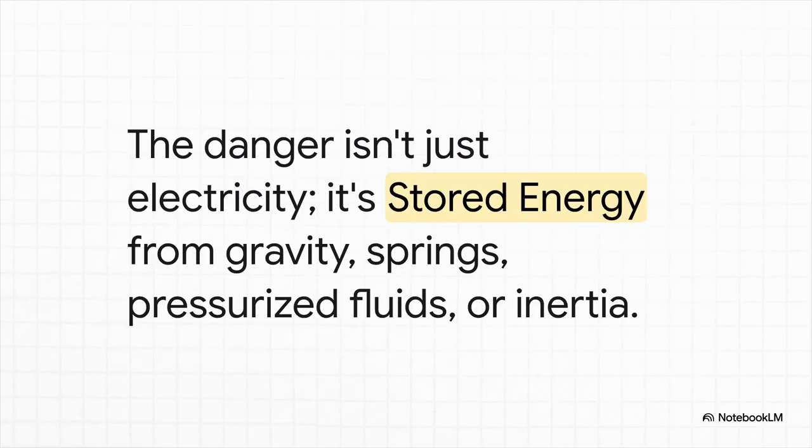And here's the really crucial point. We're not just talking about electricity here. The real hidden danger is stored energy. Think about the immense potential energy in a raised hydraulic press, or the kinetic energy in a massive flywheel that's still spinning down, or even the tension coiled up in a big compressed spring. All of that energy has to be safely dealt with.